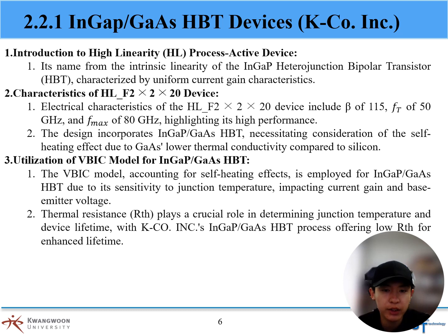Electrical characteristics of the HLF device include beta of 150, Ft of 50 GHz, and Fmax of 80 GHz, highlighting its high performance. The design incorporates InGaP GaAs HBT, necessitating consideration of the self-heating effect due to GaAs lower thermal conductivity compared to silicon.